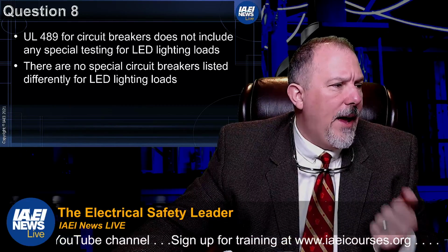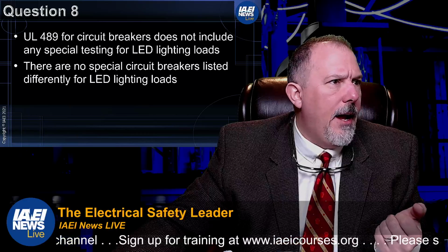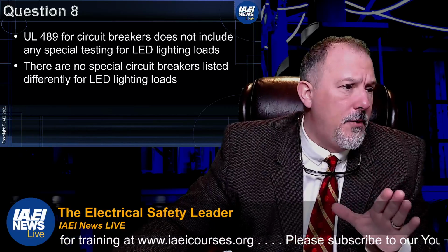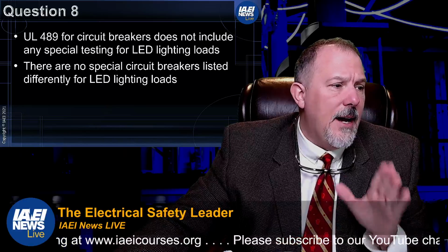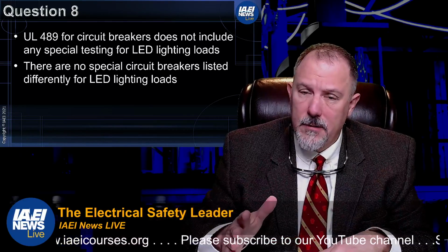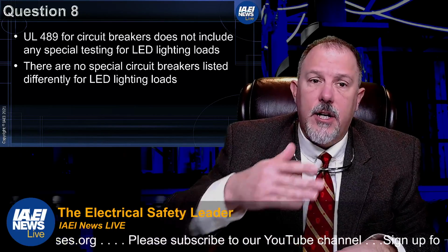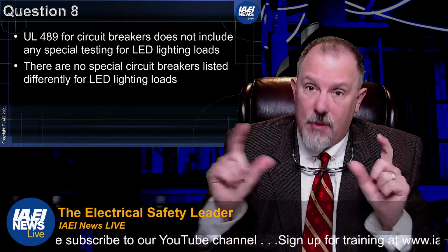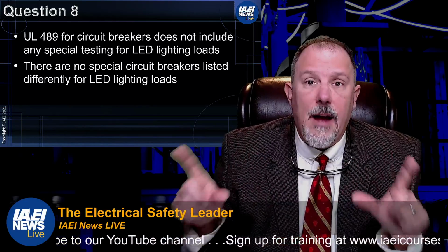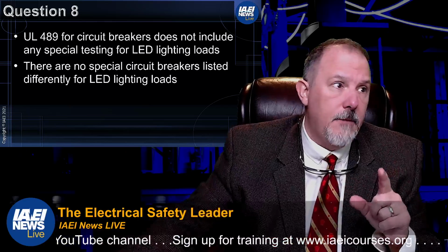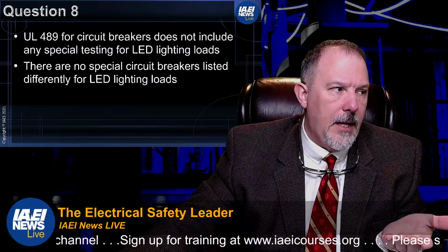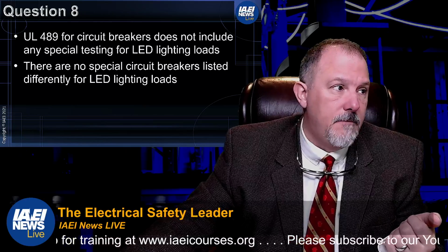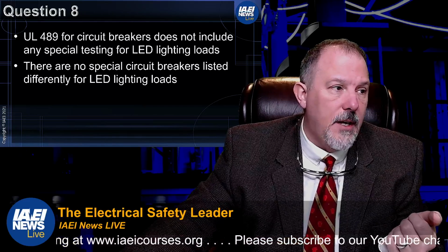I don't know if you have any words of wisdom. I have not. All I can tell you is that I have seen and I've heard of people who have had a tripping issue when they've had a lot of LED drivers on the same circuit. I can't give you any industry recognized guidance in that regard.